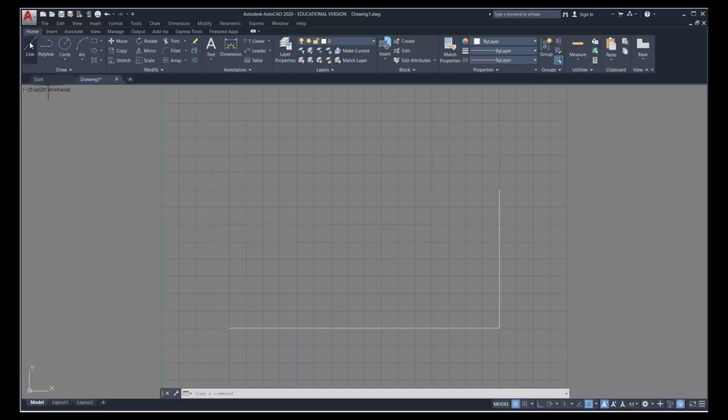I'm going to click on the line command, and I'm going to move my mouse over, and notice I have this green square. So this is a function that comes with CAD that really helps us with the accuracy of this. That is called a snap function, and we're going to explore this in detail as we go through the program, but I just want to draw your attention to it because it's very critical. I don't want to be on the end of the line. I want to be near the end, and you'll notice if I click, and you can do the same, the line snaps to that position. And that's very helpful in what we're doing.